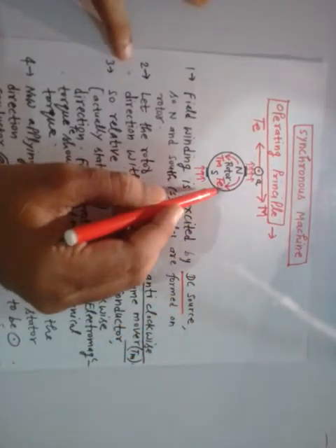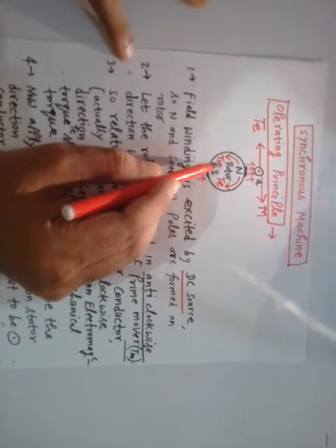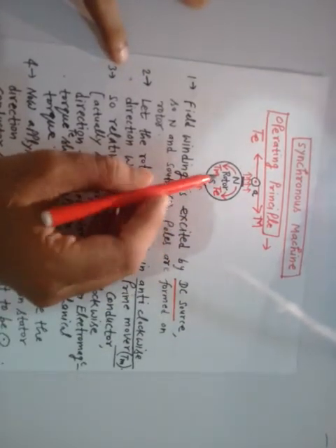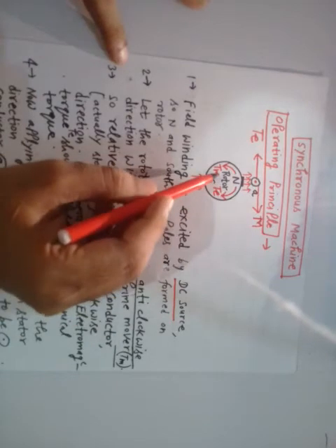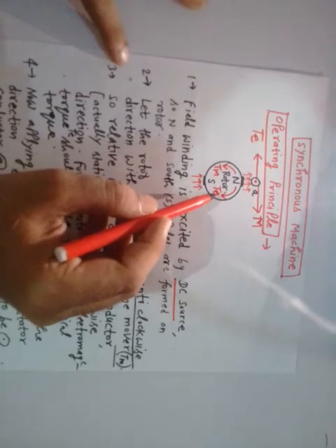I told you that the basic operating principle of a generator is that the electromagnetic torque must oppose the mechanical torque, right? This is the prime condition for energy conversion from mechanical to electrical in a generator. The same principle we discussed in the DC generator.